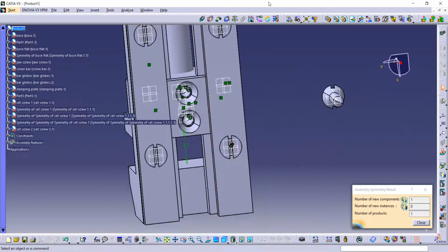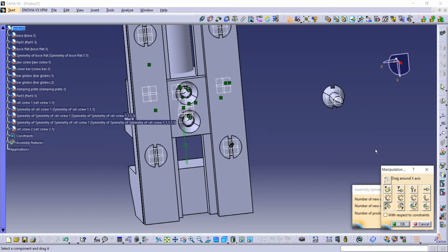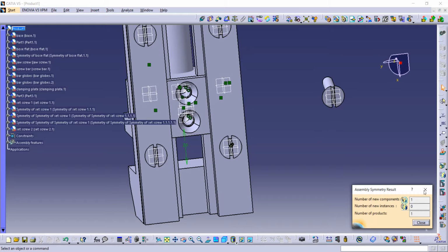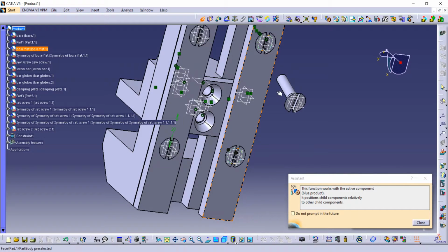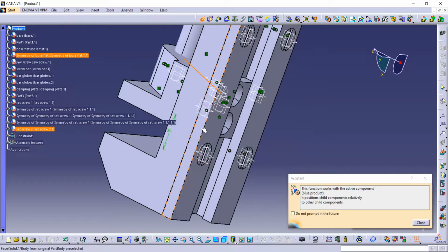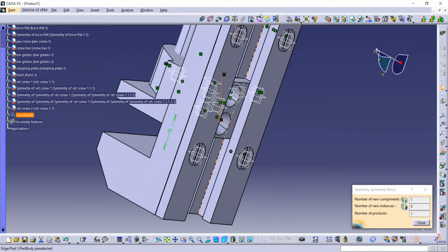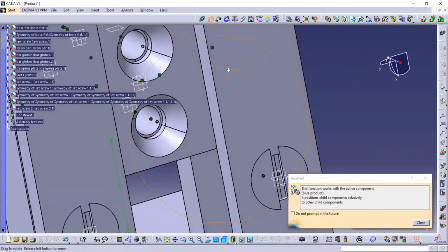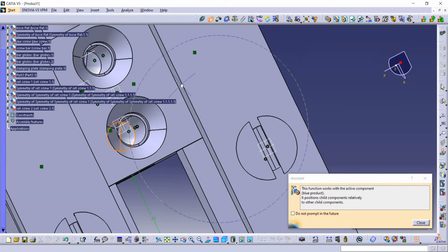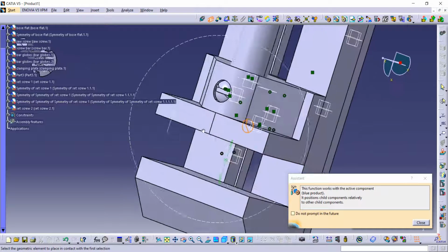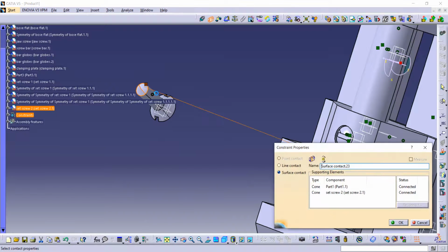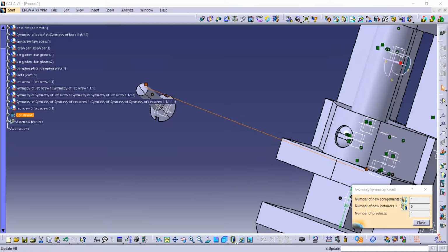First you have to move it upside down, so use manipulation option from here and just rotate it, and then now you have to use this coincide constraint, so this should be coincide with this axis, and now you have to use this contact constraint and select inside of the hole with this bottom V shape, and click on OK and update it from here.